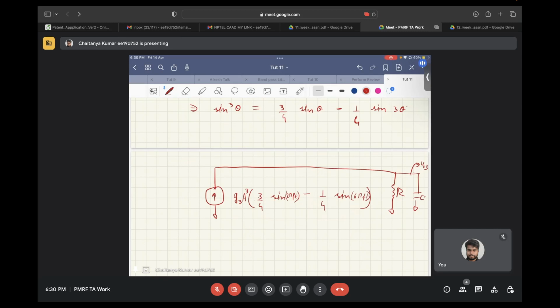A Laplace transform will give you the magnitude response basically for only one particular frequency. So here you can use superposition, because now the circuit is completely linear. First of all, you can calculate the magnitude response only due to the fundamental harmonic.